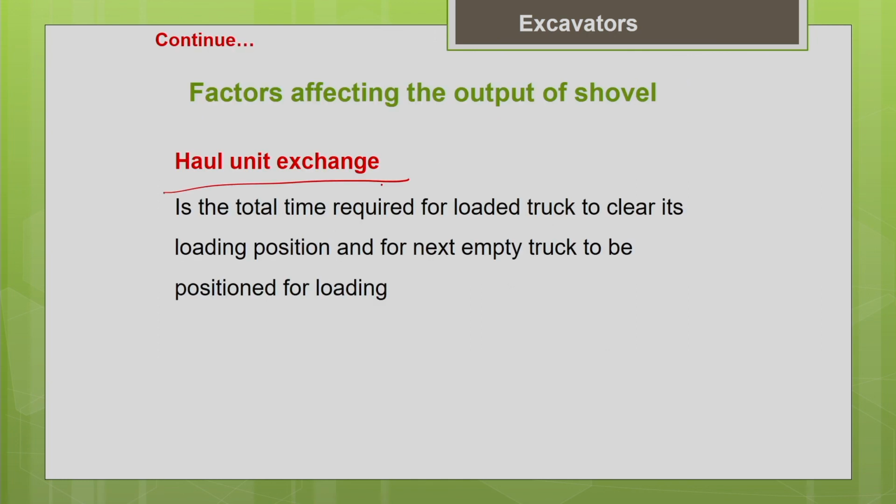Okay. Another important factor is haul unit exchange time. That means the time needed for the loaded truck to leave its position and for a new, empty truck to take the position. That is called the haul unit exchange time. Okay. So, this is also going to affect the productivity.